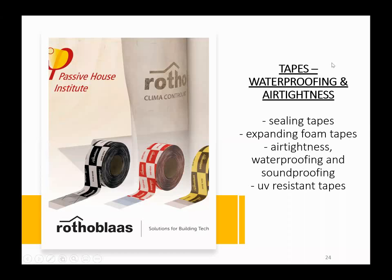For tapes, these are used for waterproofing and airtightness. You could look at any combination of sealing tapes and expanding foam tapes, and this will allow for an airtight structure, a waterproof structure, and an element of soundproofing as well. We have UV resistant tapes. We've got tapes that are available for very cold climates when the guys are working in Nordic regions. A group of our products are Passive House Institute certified, which means you can get very close to a completely Passive House certified building in timber quite easily.